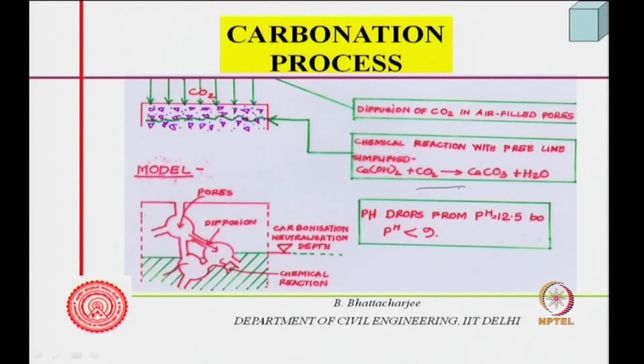But how does the carbon dioxide penetrate? It penetrates through the pores in the system, and as it penetrates, it must be a moist pore, there must be moisture here. In the absence of moisture, the reaction will not proceed, because it occurs in solution phase, carbonic acid will not form. So, carbon dioxide plus water is necessary, and therefore, water has to be there. So, it comes through the pores, water has to be there, and as all alkaline material up to this zone